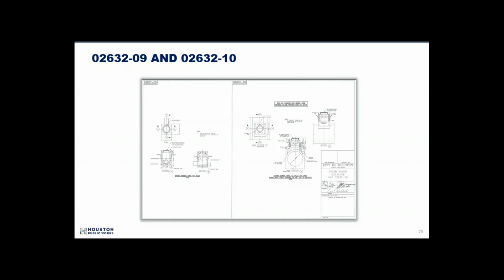On top of that, now you're seeing that if you're going to use a manhole, any sort of structure, you provide the design for that. In the precast world, if you read through our specification on precast manholes and things of this nature, you will see that it's covered in the submittal process, right? The requirement, the deliverable on the contractor side, is to submit shop drawings with a sealed PE seal on it. It's pretty explicit, pretty clean.